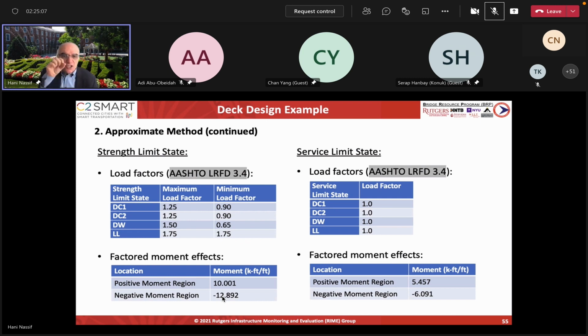So using smaller size rebar with a closely spaced would be a better way to intercept the crack. So don't try to go with larger spacing with larger rebar. Don't go to number 6 and so forth. Try to use number 4, number 5, because that would be a better way to control the cracking, depending on the spacing that you got.